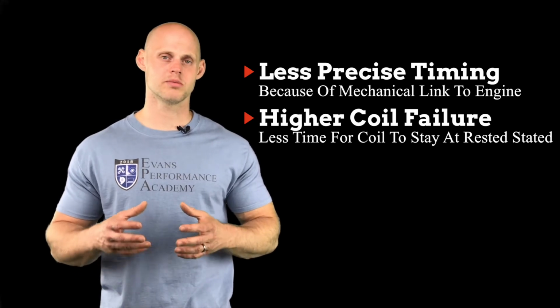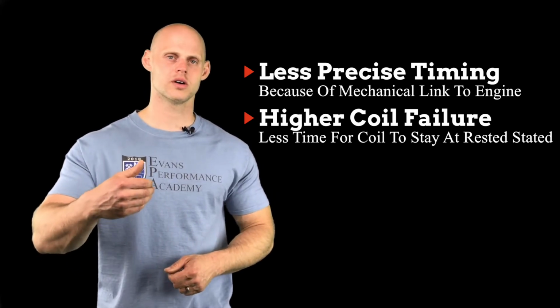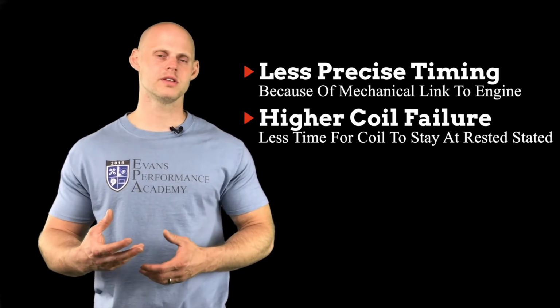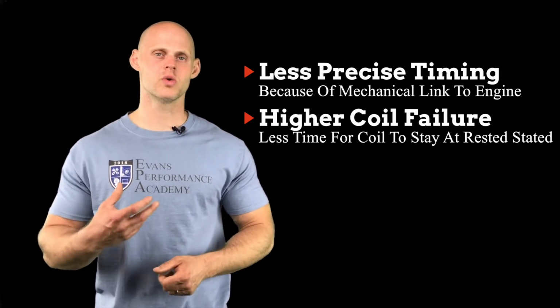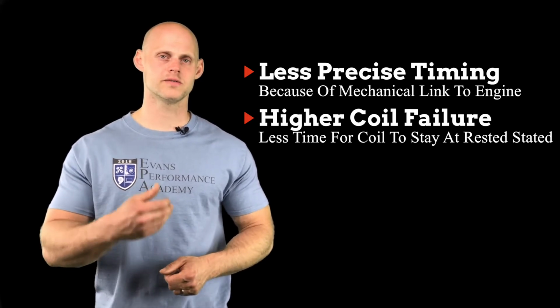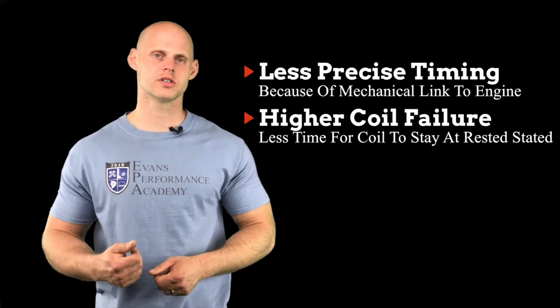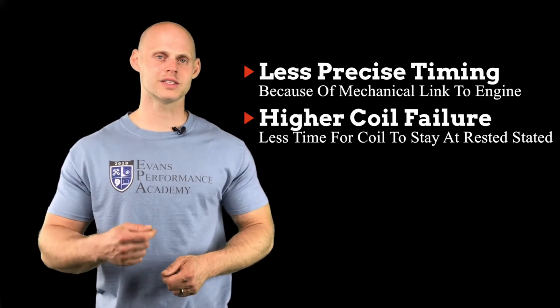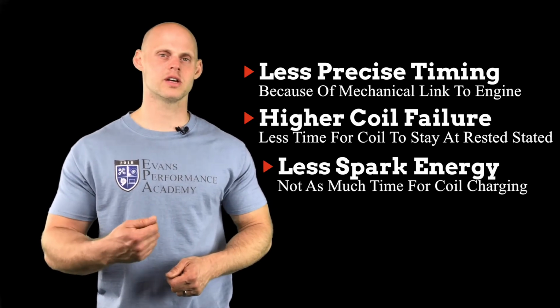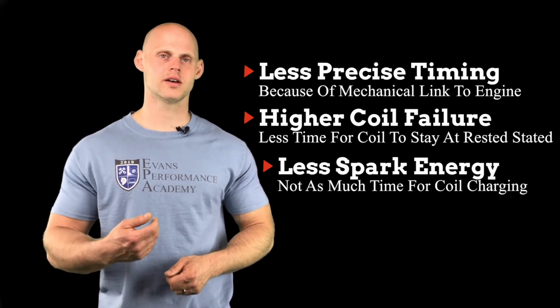So in comparison to our other ignition systems we're going to look at, the distributed spark will have the least reliability as far as our coil is concerned, because the coil is going to get much hotter because it has to constantly fire and discharge and fire and discharge. Also, we're going to be able to provide less spark energy in this style system, because again, we're going to have less time to charge the coil and build the peak energy out of it.